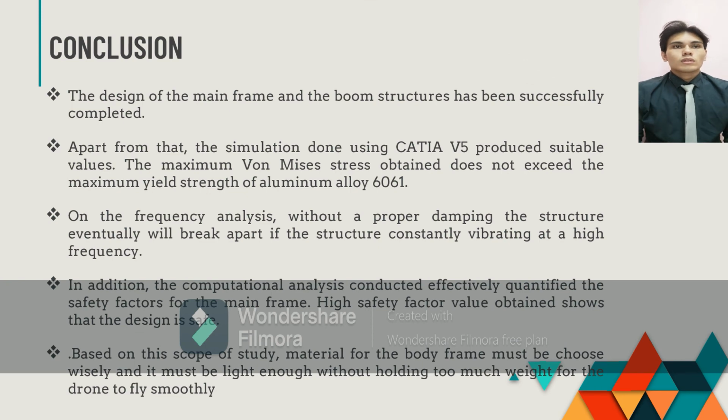To conclude, the design of the mainframe and the boom structure has been successfully completed. Apart from that, the simulation done using CATIA V5 produced suitable values. The maximum volume stress obtained does not exceed the maximum yield strength of aluminium alloy 6061.